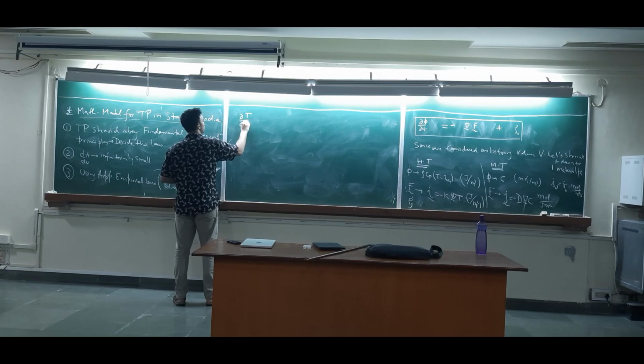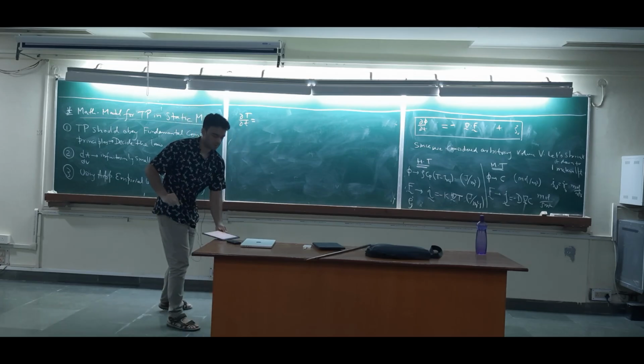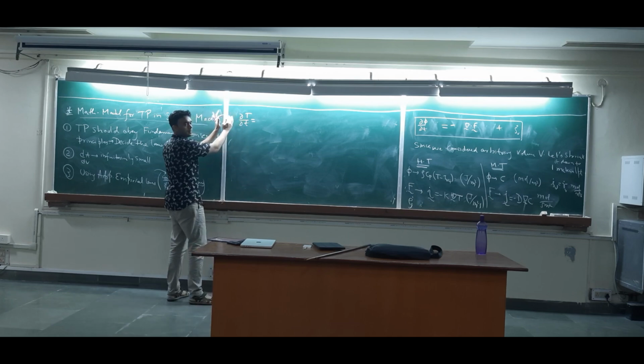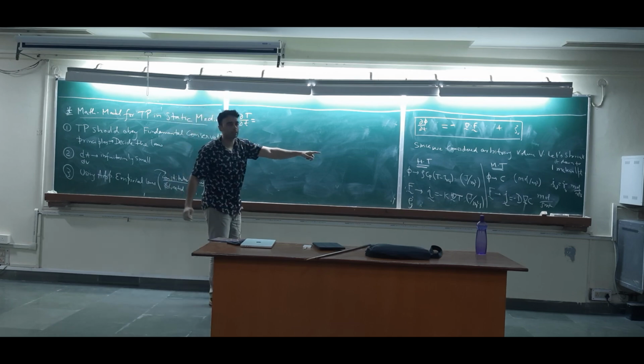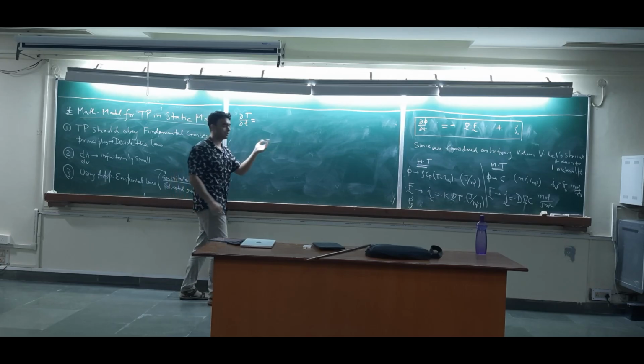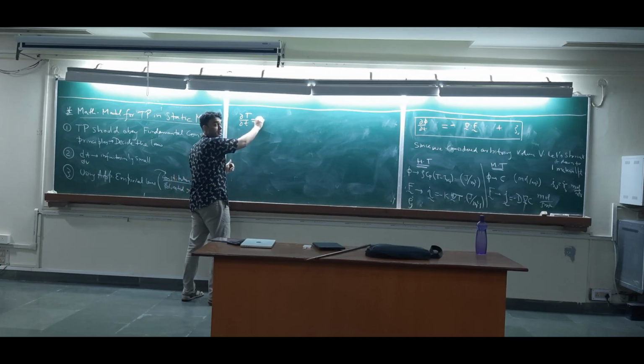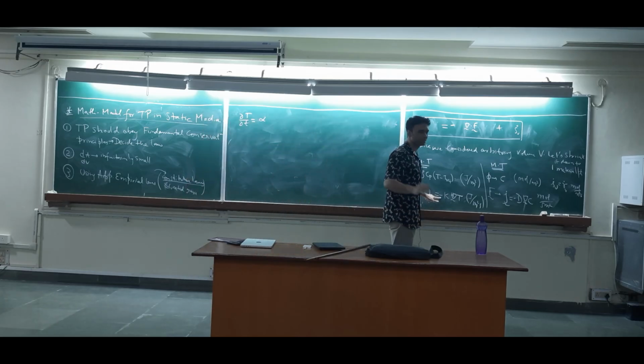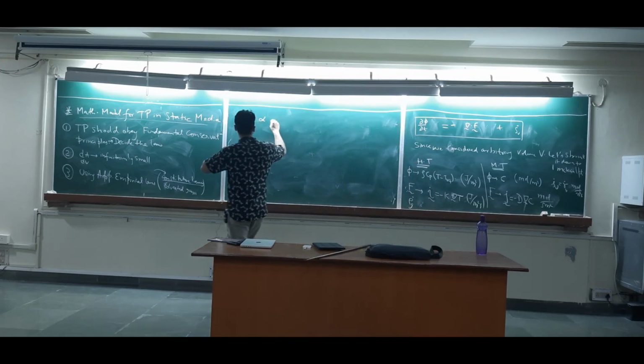So simplifying, what you will get is the following. You will have rho Cp here. Once you substitute rho Cp, you can take it to the other side. What is K by rho Cp? Alpha. Since there is a minus sign, you can do this as homework, so I'll do it quickly. This minus sign will become plus.